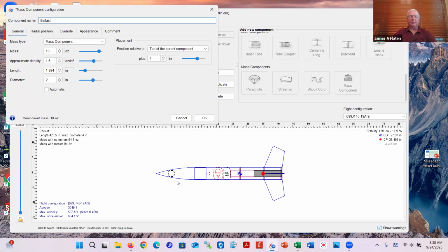The way I would actually physically do that is I would cut a hatch in the nose cone. I might need one to install this eye bolt anyway to get a lock nut on it. And then I can take those fishing sinkers, 10 ounces, stick them maybe in a plastic bag, put it through the hatch and drop it all the way forward in the nose cone, and then stuff the rest of the nose cone full with like styrofoam packing peanuts or something to keep the ballast forward and not let it wiggle around.